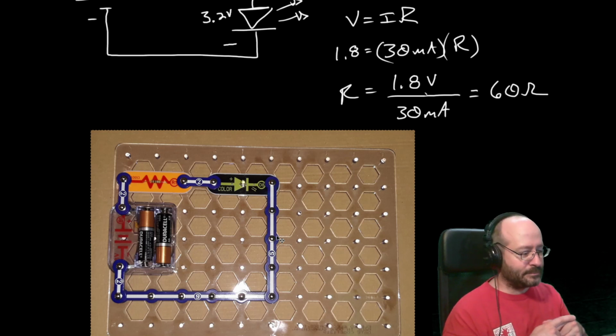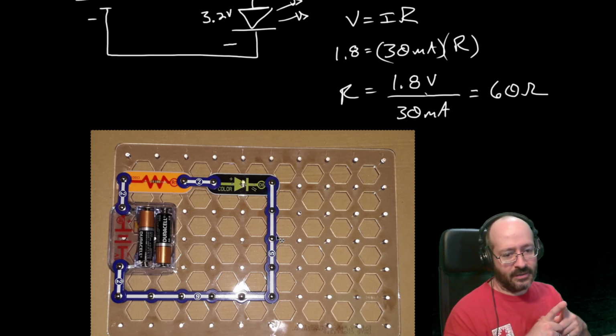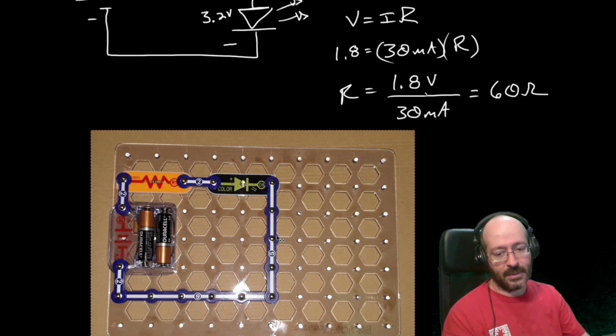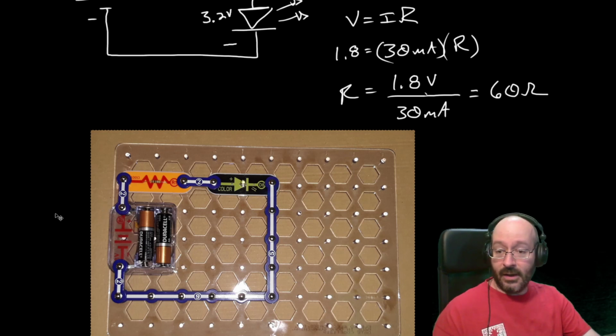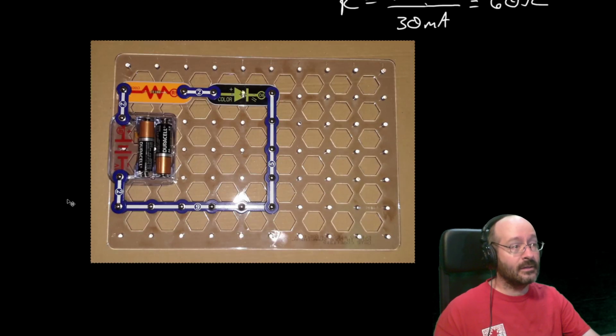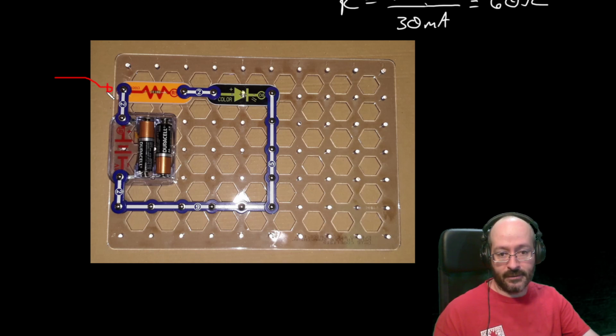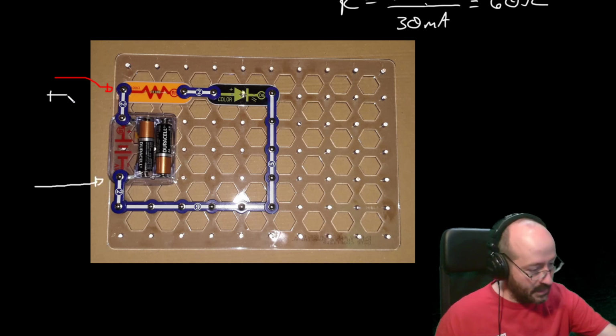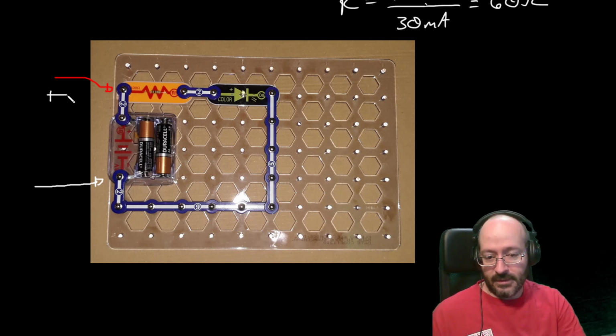Take out your multimeter, and let's take the same measurements again. Okay, so let me draw on this. Do a measurement with a red probe here and the black probe down here, and now you can just touch the snaps. I have a stylus, I should just draw with the stylus instead of a mouse. That's going to be VS.